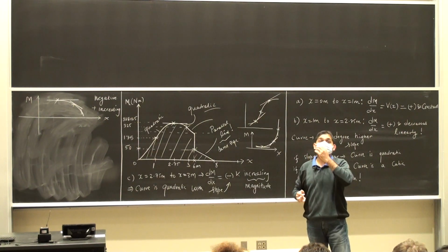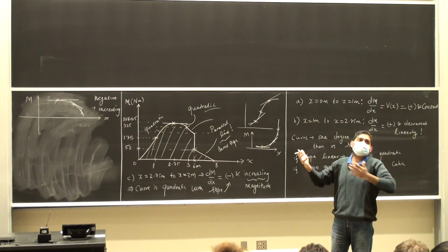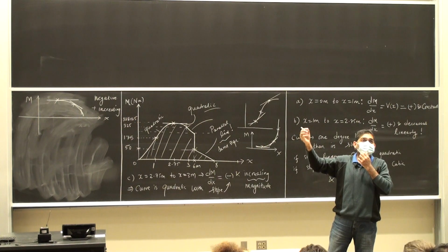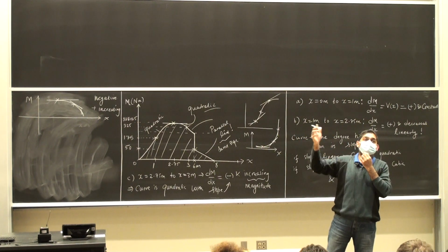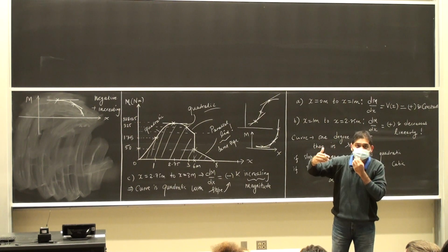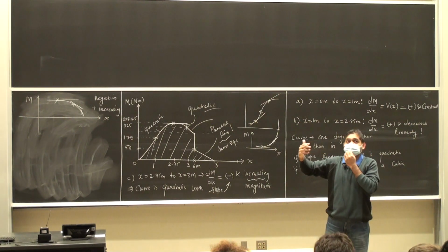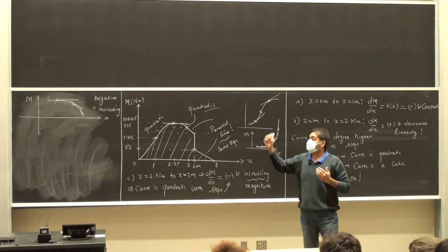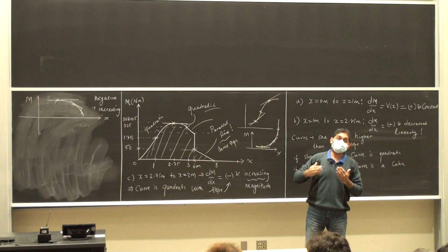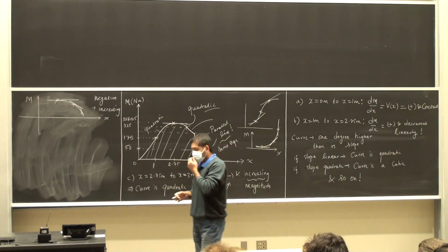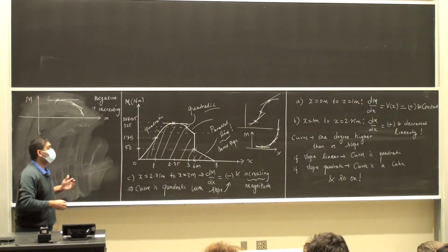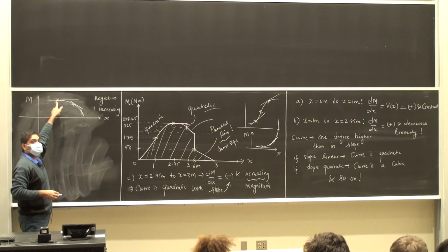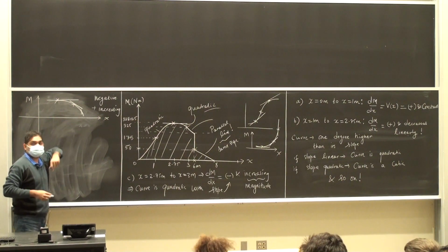Slope is negative, so the value of the bending moment or whatever quantity that you're considering, the value of that curve is reducing from where it was initially to where it is now. It doesn't necessarily make the value of M negative, it is just decreasing in magnitude, but the slope is increasing. Start off as a horizontal line of zero slope, keep increasing.